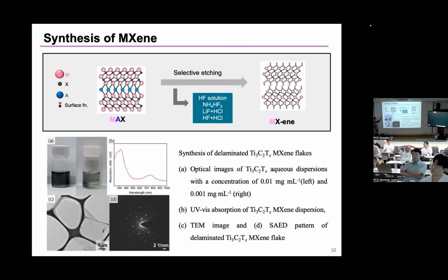This is a wet process and a very large-scale process. So we can very simply make these 2D MXene structures in large quantities. Starting from the MAX phase shown here, etching using the HF solution generates MXene solutions, and then by using spin coating, we can get the MXene 2D layer structure. In the TEM structure shown here, if you see the diffraction patterns, the crystal lines are clearly shown in these 2D MXene structures.